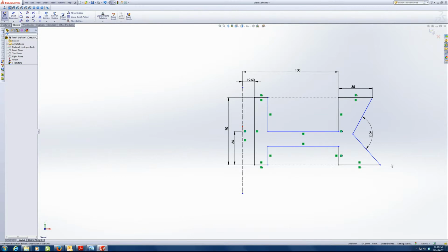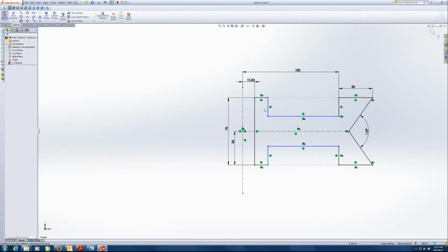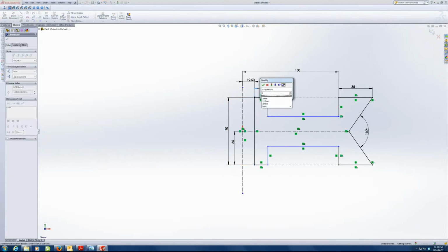What else do we need? These 2 points can be vertical. And this point and this point be horizontal, because we want that to be exactly in the middle. What I'm going to do here is draw a center line. We could also merge that point onto the center line if we drew it a bit earlier. And then we make this point, this, and this, that line, symmetric. And this distance over there is 15. From here to here is 15.